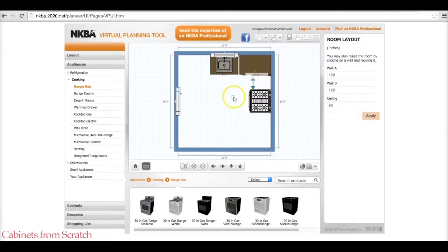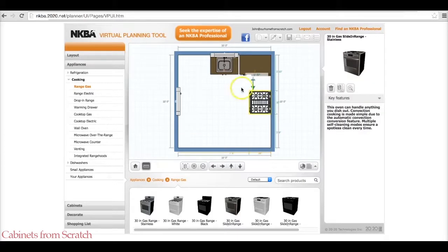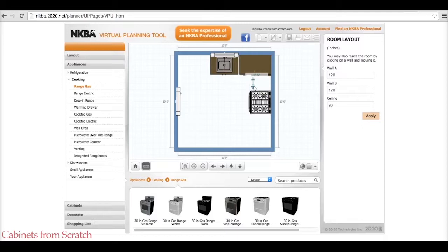Okay, so that's an odd countertop. So our cabinet size 17 inches, right? So 15, 18, this one's 17. So what I'm going to do is actually move this down another inch. This was 3 foot 9. All right, let's move it down to 3 foot 10. All right, so now that should be an 18-inch cabinet. So I'll hide the ruler. Over here, I toggle the ruler. I'm going to toggle it off. And I should be able to put an 18-inch cabinet in there.